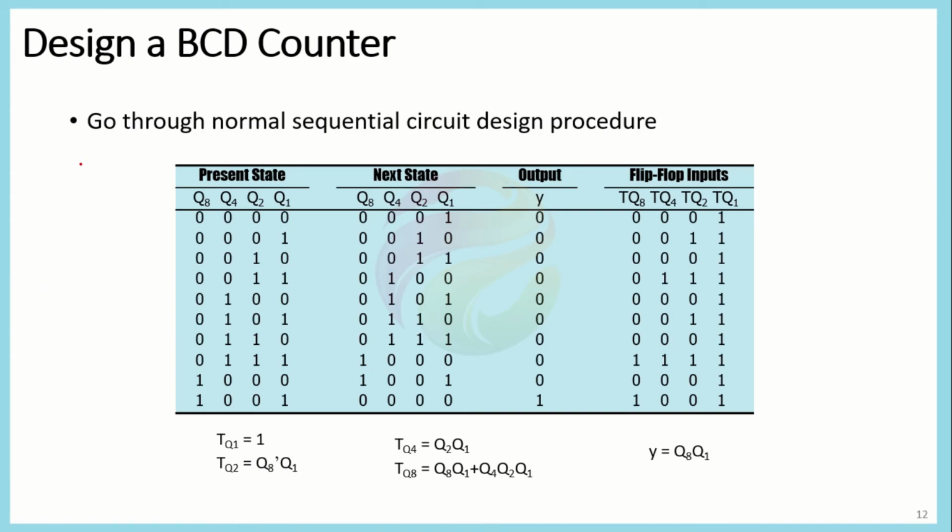This is a little bit different from the normal binary counter, because its value has to stop at the decimal value 9, and after that it should again move back towards 0. So for designing this, we could follow the pattern that we have discussed in the previous chapter.